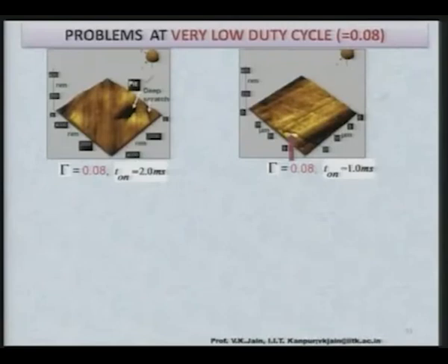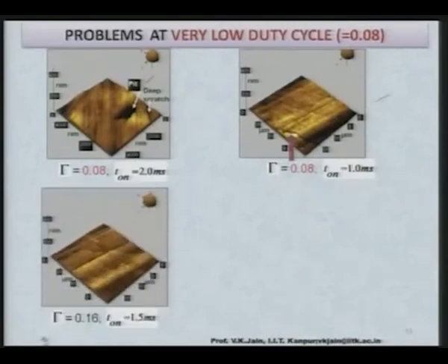Another kind of defect, if you see on the right side, the finished workpiece has a very micro nano crack, as you can see through the arrow shown over here. Some micro nano crack has been formed on the finished workpiece, although the surface roughness value is very good, but these kinds of defects may lead to the rejection of the finished component.